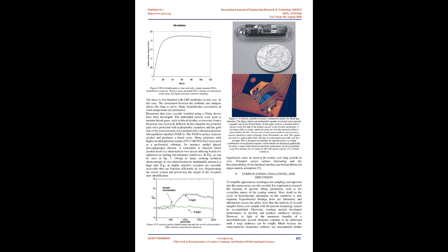2.9 Biosensors for micro-cantilever. The chromium acts as a gold binding layer. For the immobilization of silicon oxide cantilevers, silane chemistry may be used. Dip coating is the favored approach for the immobilization of receptors to obtain a strong grafting density for thiol self-assembled monolayers, SAMs, and organosilane modification. A monolayer on a gold foil is self-limited by the SAM.